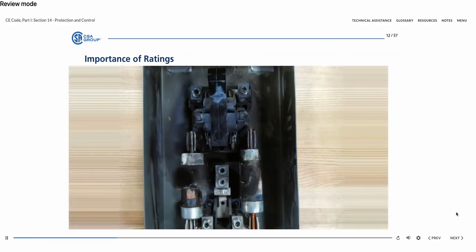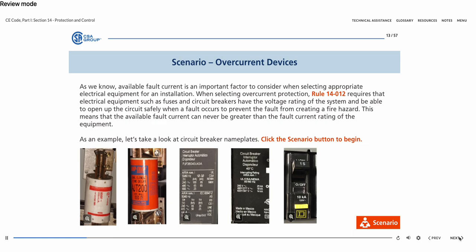This is the reason the interrupting rating is so important. The fuse installed here was not rated for this application, causing severe damage. Time for a scenario. Please read the scenario and follow the instructions to submit your answers.